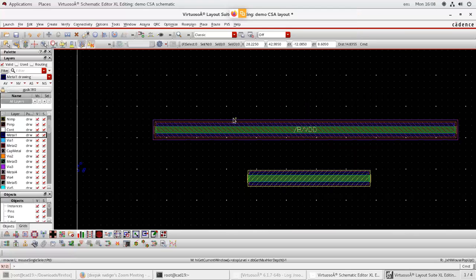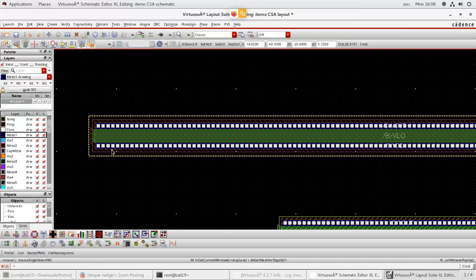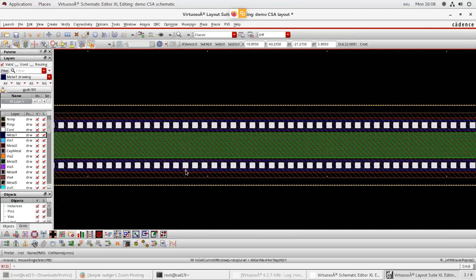So you can see in between polysilicon in green color, source and drain in blue color. That is the connection for metals. Obviously for PMOS, you have P diffusions, but for connection purpose, you have metal here in blue color.